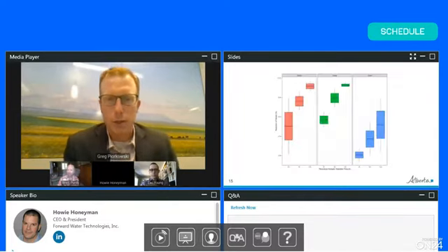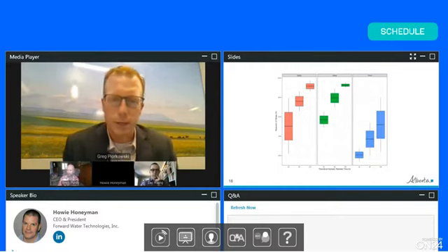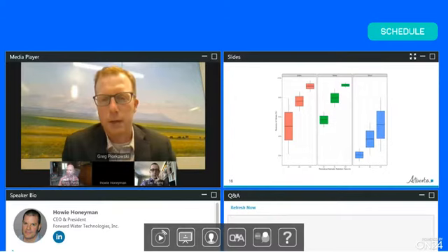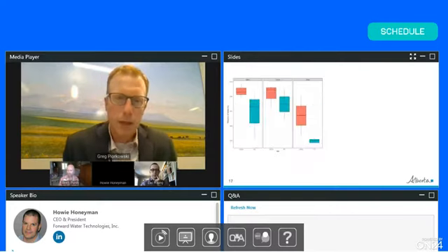What this graphic is showing is the percent reduction in nitrate, and I've broken it down into barley versus hemp versus wood. What we can see is that the agricultural residues range from about 50 to about 90% removal, depending on their hydraulic retention time, which is greatly higher than what we observe for wood. So the agricultural residues do have a much greater performance with respect to nutrient removal than our wood.